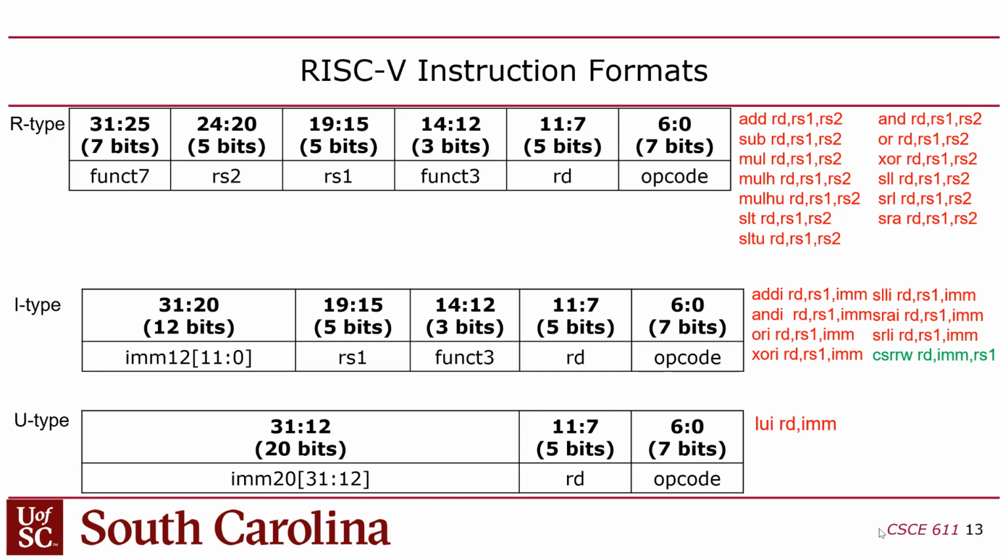Well, obviously, if you need more bits, then you can use more bits, but then it gets translated into a pseudo instruction. So the assembler will end up adding one of these load upper immediates in there for you to be able to load more bits. So 12 bits is your limit for one instruction. If you need more than 12 bits in a constant, then it gets split into multiple instructions that load a register. You guys with me?